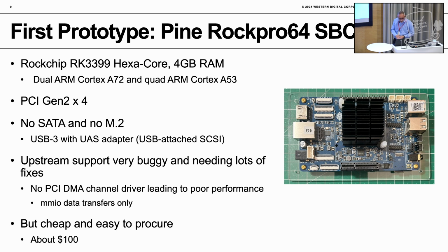And the support for this was upstream, but unfortunately it turned out that the endpoint side of it was extremely buggy. So we had to do a lot of debugging work to get that to work. And also there is no PCI DMA channel driver upstream, meaning that the only thing we can do is MMIO data transfer. So plus the fact that it's PCI Gen 2, it's extremely slow. But it's cheap and easy to procure, so we started with that.